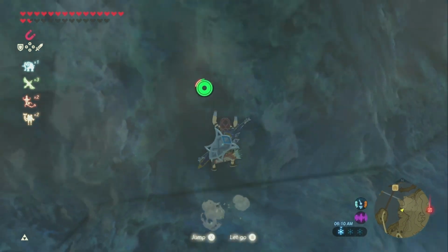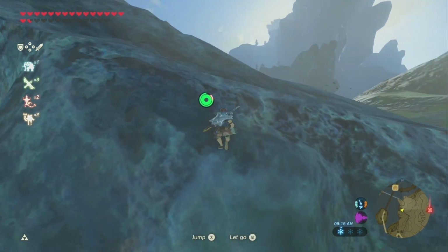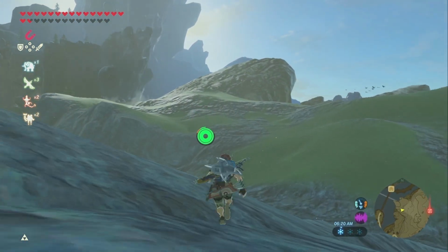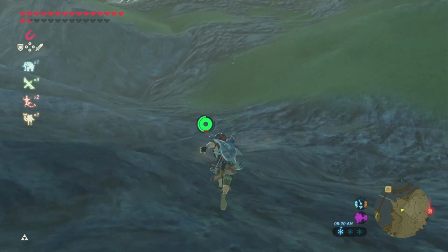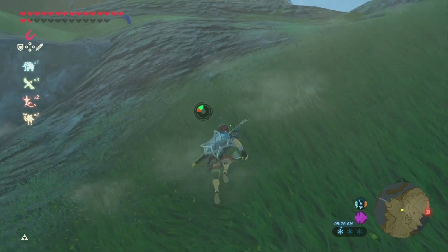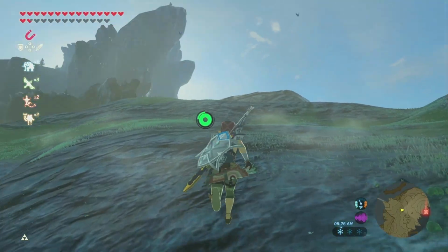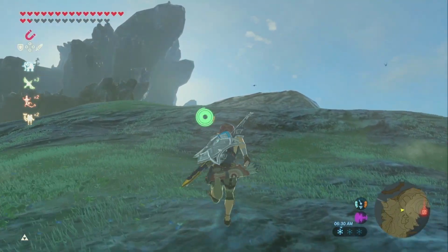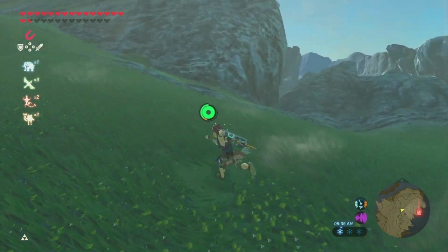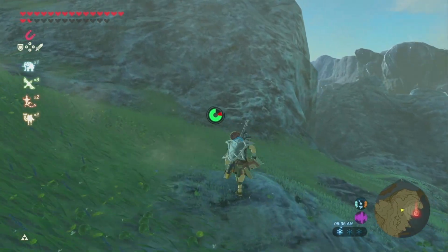Power vented water heater. Operating sequence for fan-assisted units. Thermostat calls for heat. Fan comes on first. Pressure switch proves the fan is on. The ignition system activates the burner. Flame is sensed and the system operates. The thermostat is satisfied. The burner is shut off. 30 to 60 seconds of blower post purge.